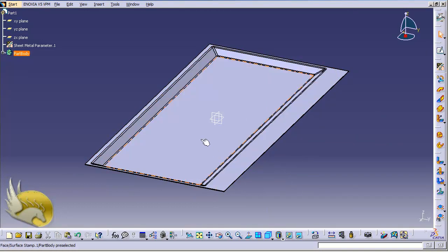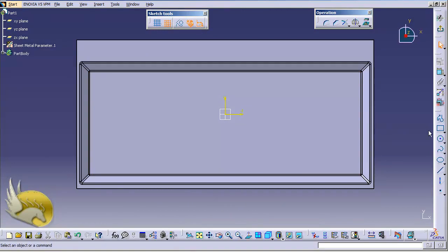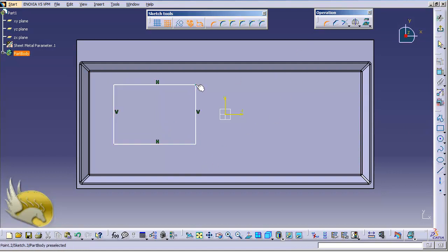Now I have a sunken area here. I click on this to create the third sketch. I go to sketch environment, and the first thing that I want to create is a rectangle, and I want to have round corners there. So again, I create this rectangle like this, and click on corner tool, select this edge, press escape again, because I selected the line mistakenly. I select this edge again, click here, again the corner tool, this edge, and click here, and all the radiuses are going to change because I want to have about 75 millimeters of radius in them.